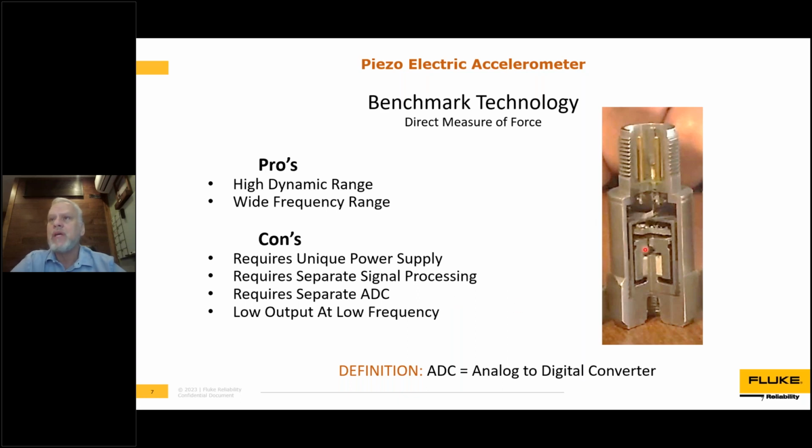The other thing I want to note here, and we'll talk a little more about how this works, is a typical accelerometer with the crystal in white, and the proof mass, the cutaway here showing the mass that surrounds that shear mode crystalline device. Interestingly enough, within this stainless steel package that you get your sensor in, there's also an amplifier. That's not always the case, but in most of today's traditional accelerometers, once that amplifier's inside, you can have cable lengths from 10 foot all the way to maybe 500 foot without any significant degradation in signal. That's the advantage of having this style of accelerometer.